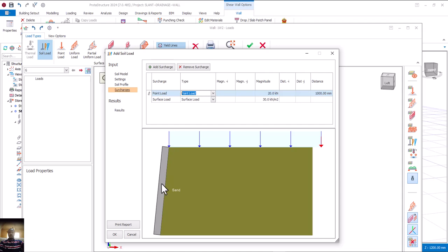Now, if we create a hole that passes through this concrete wall, you normally see this kind of thing, a bridge for water to escape, seepage, something like that. Once the pipe passes through this place, the point at which the pipe is resting on the column is a point load. That pipe is acting as a point load on this particular wall. But in this case, we don't have such, so I'll remove this one.